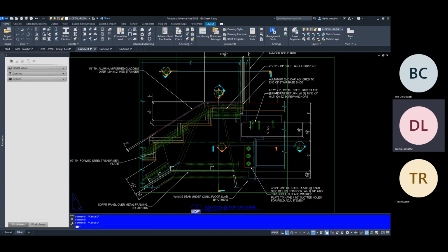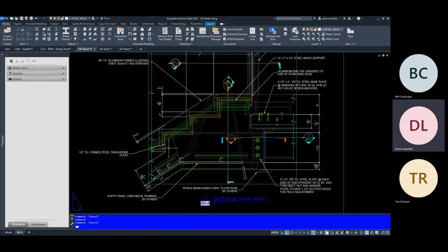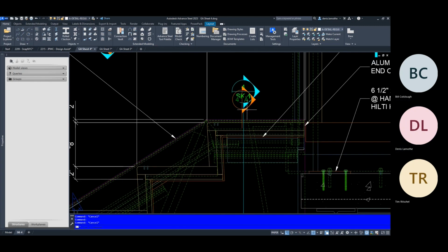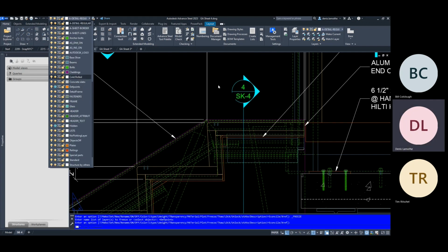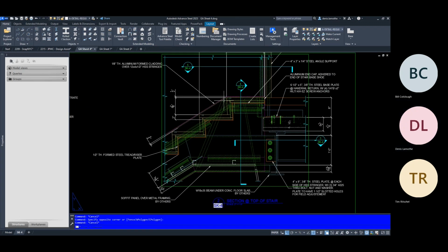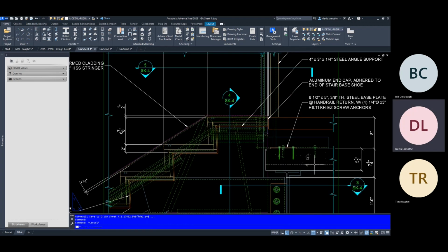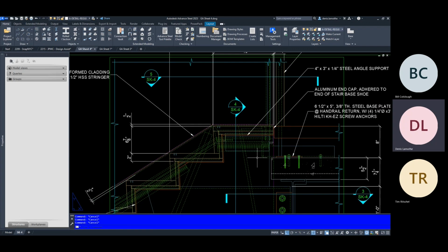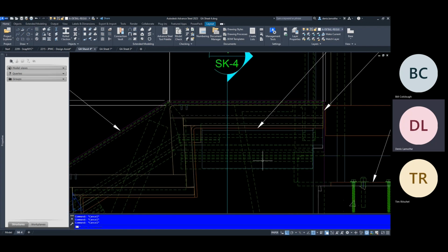I haven't completed this set. These are design assist drawings, but I haven't completed this yet. But also, make sure that you're including things like your weld symbols. These are Advanced Steel generated labels here, but I typically hide that and create my own just to reference proper numbering styles and whatnot. But again, try and keep it clean. The size of your hatch should be such a small scale that it just looks like one big solid mass. Your line type scales, I know Advanced Steel is being a little fussy with me as well, should be set in a way that if it's a hidden line, it looks like a dashed line and not just one solid line continuous across.